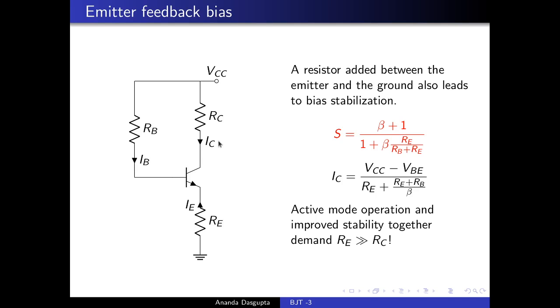If the voltage drop across RC is already too small, then if you apply a signal, which we haven't done yet, but we will, after all that's what this amplifier is for, the current IC will go up and down. And if the voltage across RC is really rather small to begin with, fluctuating IC will drive that voltage down to zero. But that means that the voltage of the collector hits the maximum possible value, which is the bias voltage. It will not go beyond that.